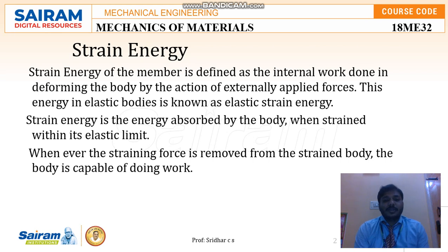See, whenever we release the load, the body automatically regains or reabsorbs the stored energy and comes back to its original position within the elastic limit. So within the elastic limit, stress is directly proportional to strain, so there will be no permanent deformation. Next, whenever the straining force is removed from the strained body, the body is capable of doing work. Yes, even after the removal of the load, the stored energy can do its work. That is one of the major advantages of strain energy.